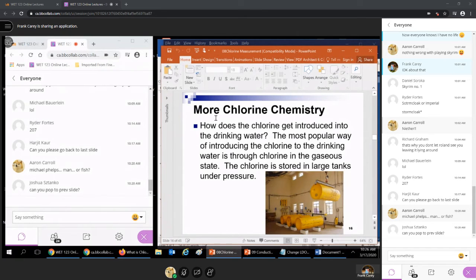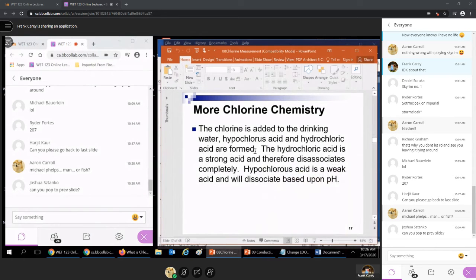In the chlorination lab, I've mentioned tonners before. These, incidentally, are tonners. So they're 1-ton tanks full of liquid chlorine. How does chlorine get inside our water system? Tonners are by far the most used method, by actually injecting liquid chlorine into the water system.